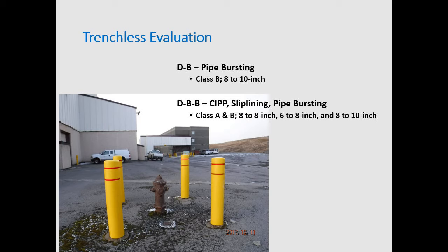Do we want to look at slip lining? I talked about the 16-inch on the southern portion of the island, right next to the 8-inch water line. There's a 16-inch that was installed for fire protection. Long straight runs. We offered to them, hey, you could do a slip lining here, and realize the benefits of not having to provide temporary water. We can put a new pipe inside the old pipe, grout it in place. You might realize some real cost savings.